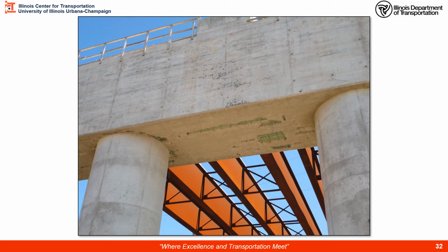You can see here a lack of consolidation around this pier. And this flat area here, there's some bare bar, also some honeycombing going up through this area. These were repaired at the contractor's expense.